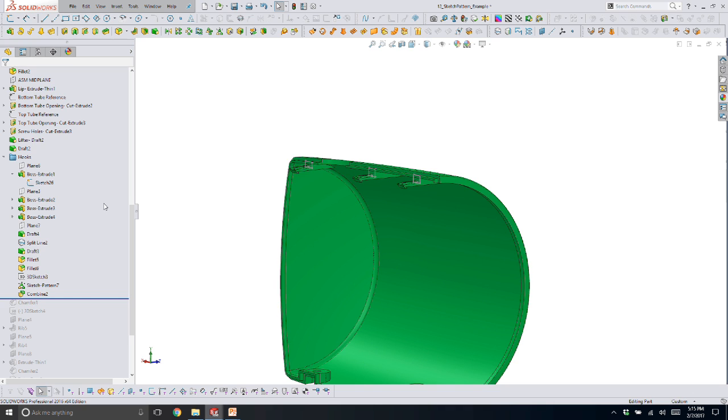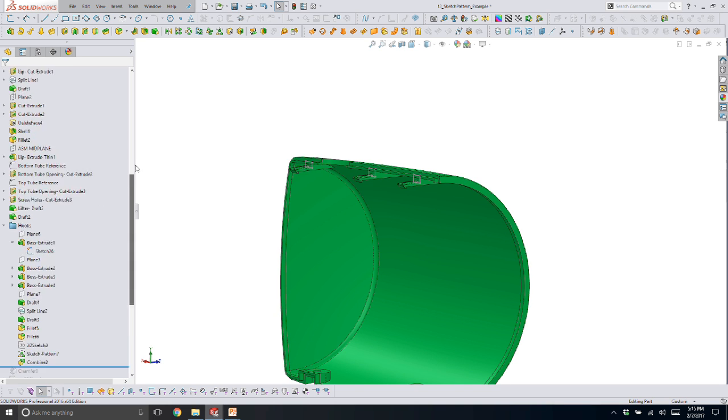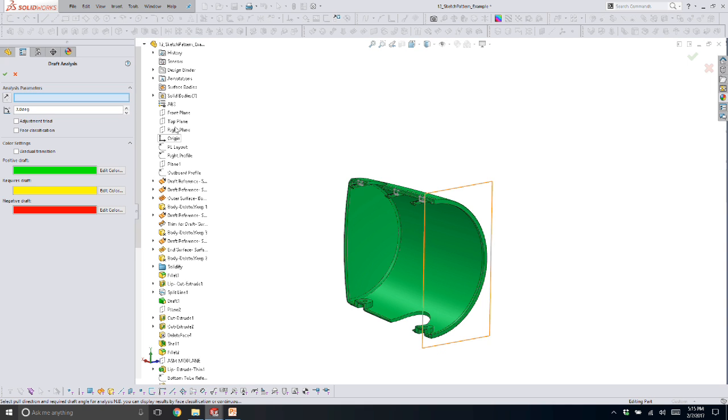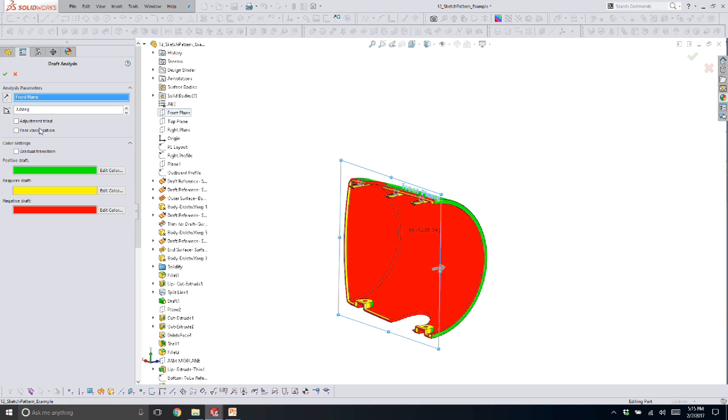Remember, and I can't stress this enough, and we've reported it for years to SolidWorks that we think it's a bug, that patterned draft does not pattern. It does not mirror the feature itself. Body geometry always correctly patterns because we've applied the draft to an individual body, and we're just patterning that geometry, not the features, which are the instructions the SolidWorks uses to actually create the draft on those faces. And that's why draft analysis is just so important when designing plastic parts, and just always be checking your work, going in, making sure that we've got correct draft everywhere.